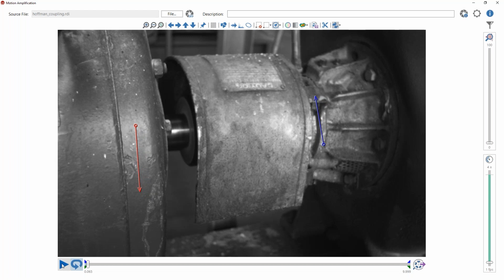We might do cross-channel phase with 2 accelerometers and then say, they're 180 degrees out of phase, give you a number, 90 degrees, 180, right? And that number tells you something. I think that's, for me, the least intuitive, sort of in a scale of things.